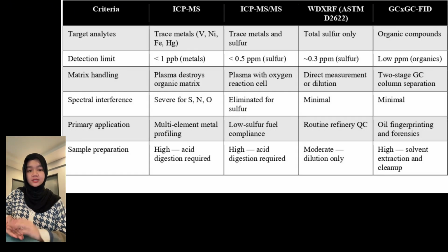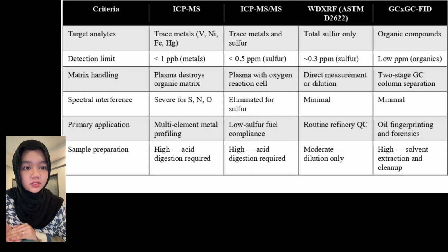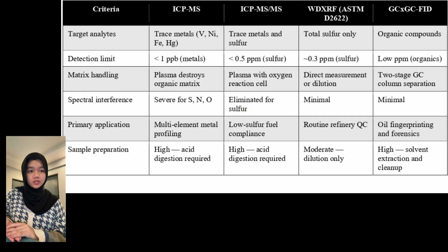WDXRF under ASTM D2622 provides a reliable and commercially standardized method for total sulfur quantification, but provides no information on trace metals or the molecular composition of the sample. GC-FID offers unparalleled resolution of individual organic compounds but cannot quantify inorganic elements.